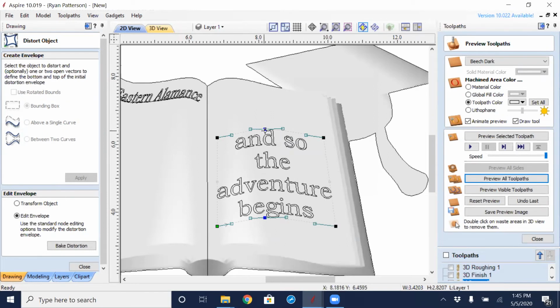That now created this Bezier type of curve to where I could now select just these two control points and moving those down. We can see how it's kind of curving around, and might want to even take these two here and move those up. And this side here.